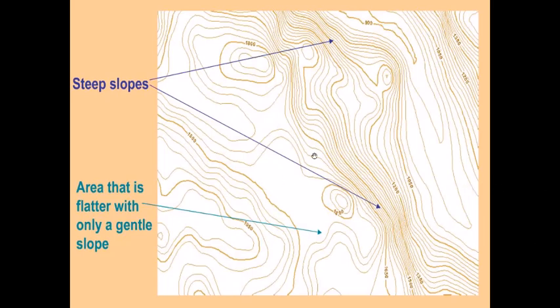Something that we've discussed so many times, that when you have steep slopes, the contours will be closer, and when the land is flatter, that means the contours will be widely spaced, and you can have these empty spaces in between. That means that the land probably over here is of such elevation whose contour line you decided not to draw. And that basically means that the land is pretty much flatter. So you get an idea.